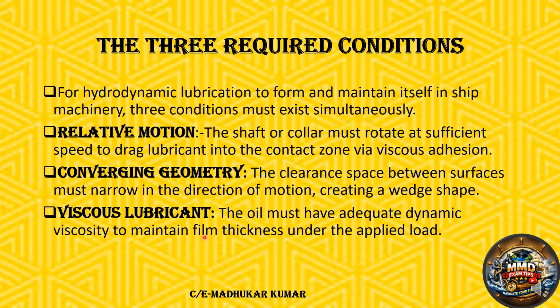That's why on board ship we have lube oil charts for the various machineries, and accordingly, not only for this load carrying part but also as per the other lubrication requirements. The chart basically gives the complete idea of which machinery requires which type of lubricant, whether it is hydraulic oil, main engine system oil, generator sump oil, cylinder lubrication, purifier, or compressor.